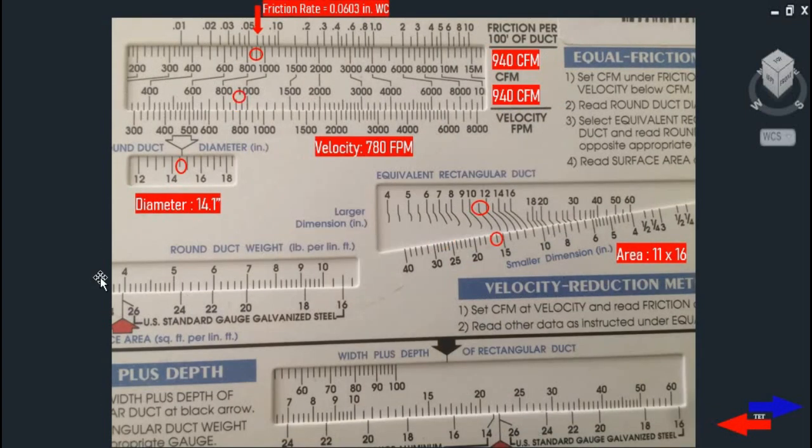The next one at a friction rate of 0.06 for the 940 CFM, we have a round duct diameter of 14 and a quarter inches with an air velocity of 780 feet per minute and an equivalent rectangular duct of 11 by 16 inches.